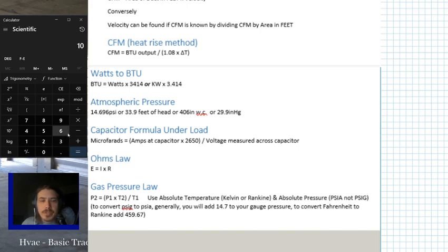So, as an example, we had a 10 kW heater kit. We put it in emergency heat, put the fan on. A heat pump usually runs in single speed anyway, so it doesn't matter, but you have your fan on and you run that 10 kW heat kit in emergency heat. 10 times 3.414. You'll also see it written as 3.412, 3.413. They're all really close. It doesn't matter. So 10 times 3.414.